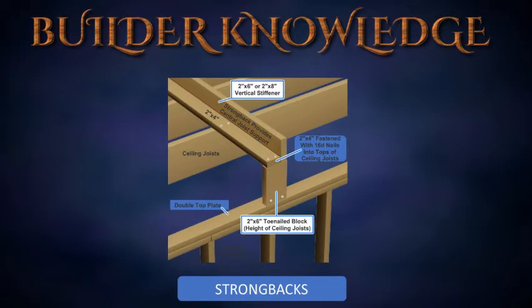Strong backs. Strong backs are more effective than rib bands for preventing ceiling twisting, bowing, or sagging. They are built with 2-inch by 6-inch or 2-inch by 8-inch material, nailed to the side of a piece of 2-inch by 4-inch material. They are then blocked up and supported over the exterior walls and interior partitions. They hold the ceiling joists in alignment and help support joists at the centers of their spans.